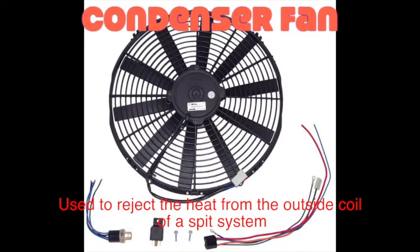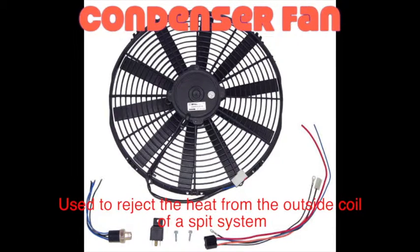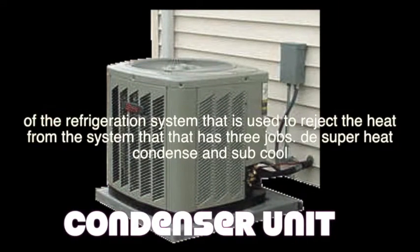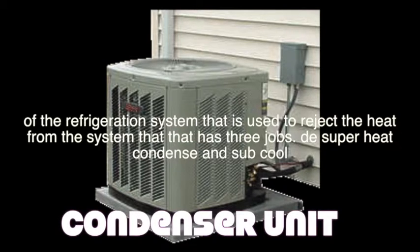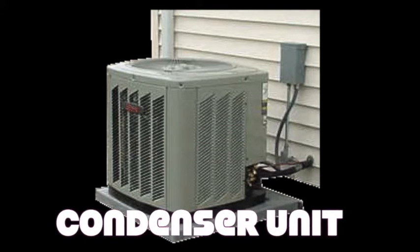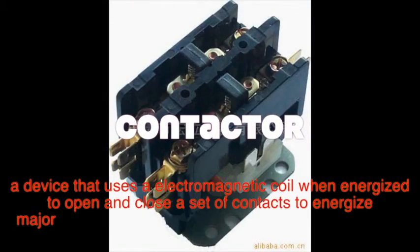Condenser fan: used to reject the heat from the outside coil of a split system. Condenser unit of the refrigeration system that is used to reject the heat from the system, which has three jobs: de-superheat, condense, and subcool. That's the condenser unit.